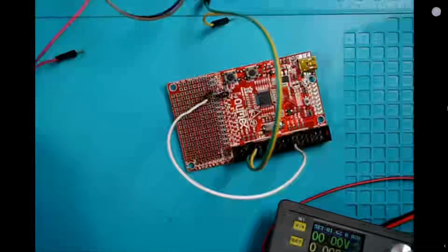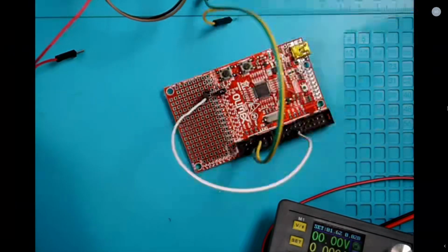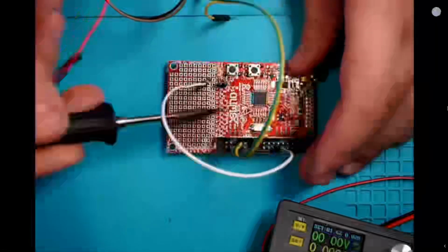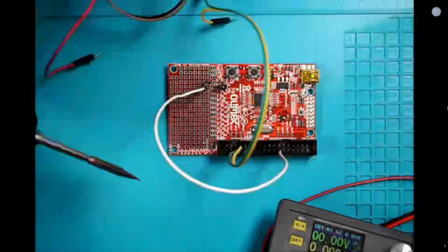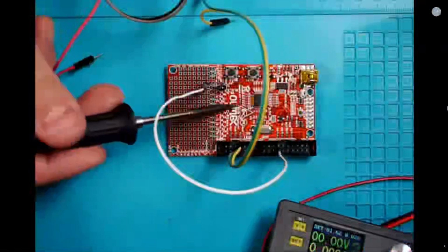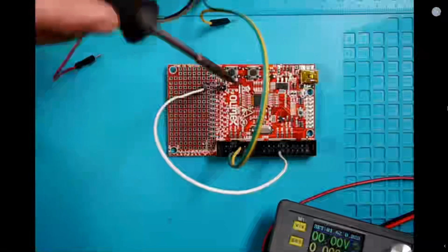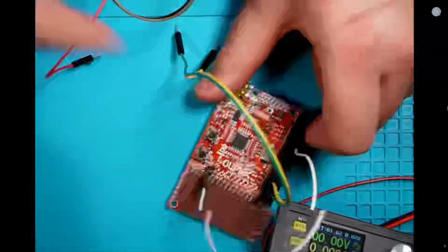Also let me make sure my irons are hot. The first modification we're going to make is we're going to remove 2 capacitors. So we actually have a capacitor right here. Let me see if I can get just a little bit more zoom. No, unfortunately I can't. So we have a capacitor right here, and we also have a capacitor right here that we want to remove. So for this, I'm just going to move this out of the way, and I'm going to move the other cable out of the way.